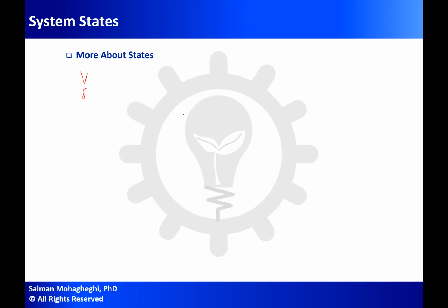One example is if you have a transformer with a tap changer, the tap position would also have to be a state, and you would do exactly the same thing that I mentioned. You would have to include the tap position T in your equations, and find those nonlinear equations h of x's, find the derivatives, and repeat the whole thing just like you would for another standard state of voltage magnitude or phase angle.